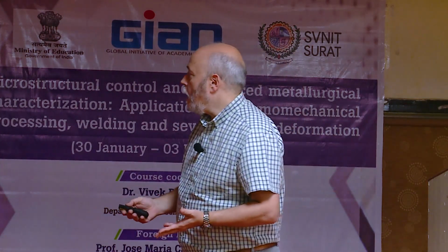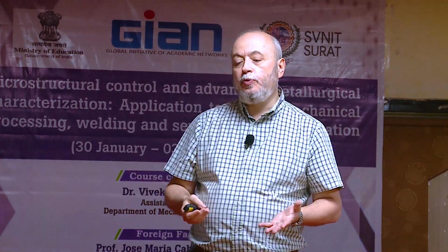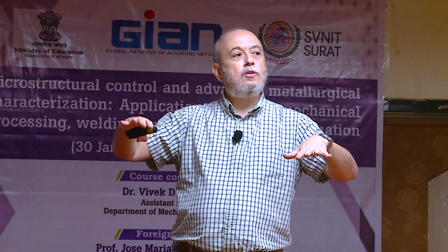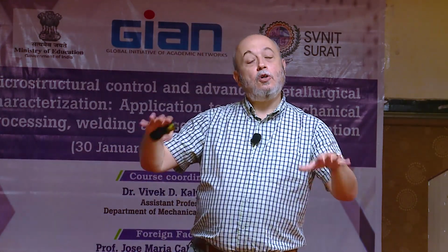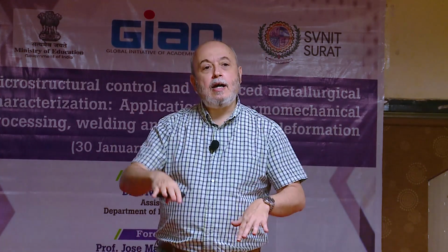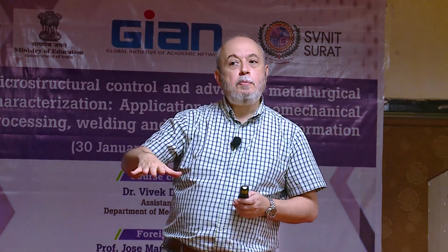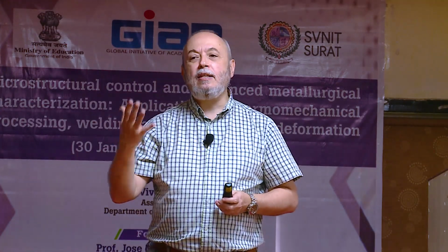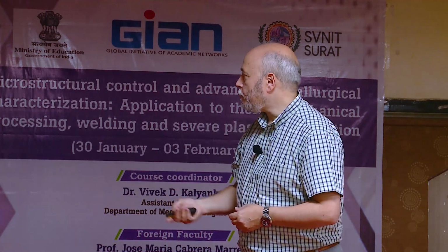Hot stamping. Usually when you want to deform a sheet, a flat format, usually you think in doing that at cold conditions, at room temperature conditions. Now most of our cars are coming with components which are hot formed. And during the hot forming process, we are going to change the microstructure in such a way that we will get a very strong and hard material. We will see in a moment.